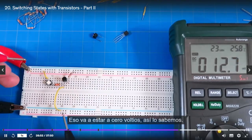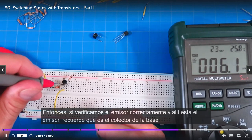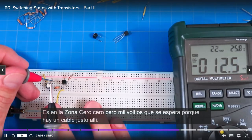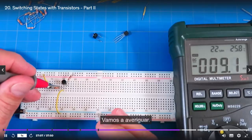So that's going to be at 0 volts, so we know that. So if we check the emitter, and there's the emitter right there. Remember, it's emitter, base, collector, very carefully. It's at ground, 000 millivolts. That's expected because there's a wire right there. Now, what's the base at? Let's find out.